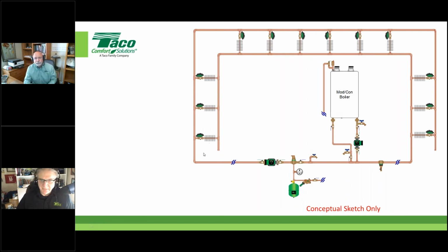And another question here, and I'm not sure if we can provide a satisfactory answer, but what factors do we need to keep in mind with a two-pipe hot or chilled water system? Well, again, from a chilled water standpoint, we're dealing with tighter delta T's. We might be dealing with something like 12 or 10 or 8. So the flows are going to be higher, but we're still moving water. And hydraulically speaking, you still have valves opening and closing. The circulator is going to look at it pretty much the same way. So there's not a lot of difference there other than the pipe sizing based on those tighter delta T's and higher flow rates. Very good. That's where we're at. Go get them.